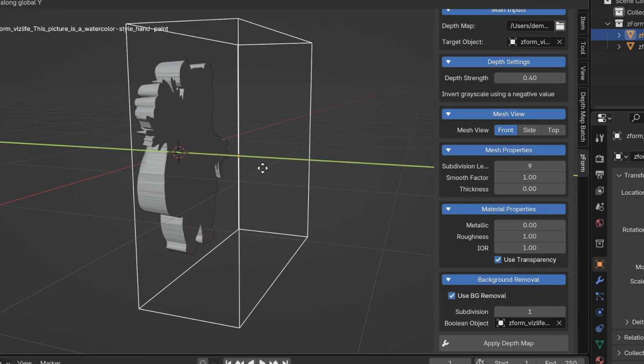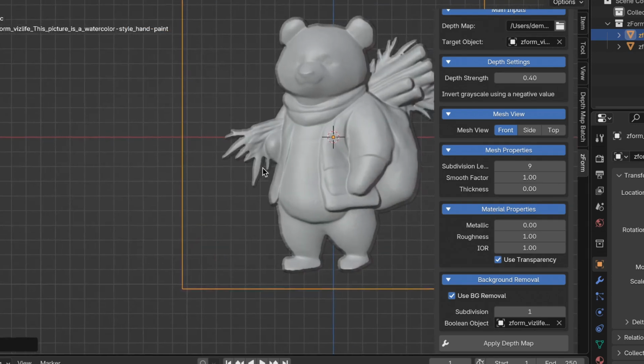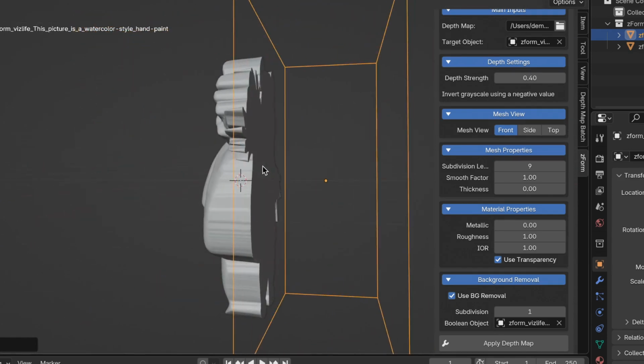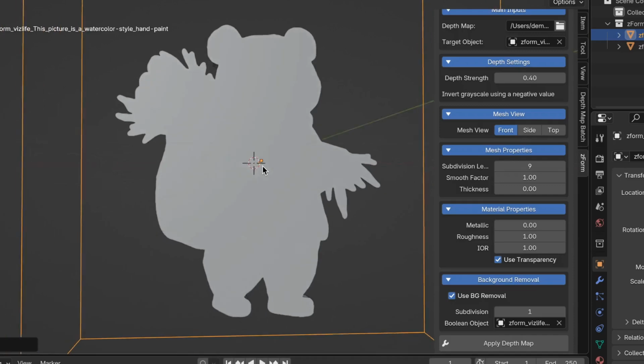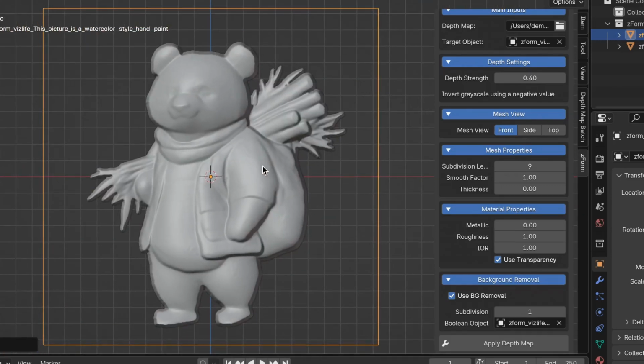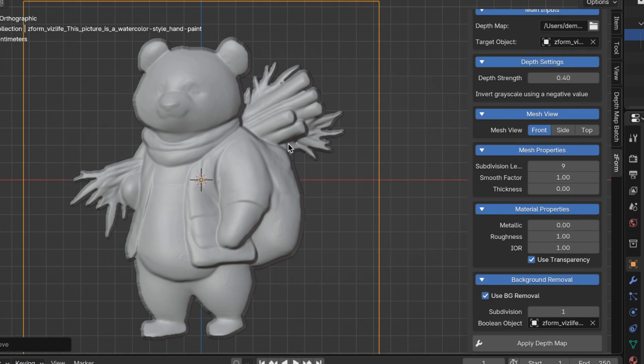So I'm going to press Enter and then I'm going to go back into the front view to see if they were removed. Let me move in a little bit and everything looks pretty good. Let me go to the backside again. The outlier vertices have been removed. So that's how you do it. If indeed the main object in the scene is touching one of the edges of the image, I have a separate video on how to handle that, and I'll include a link in the description.